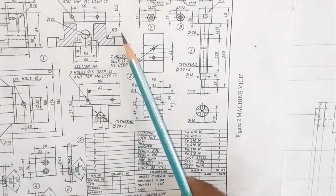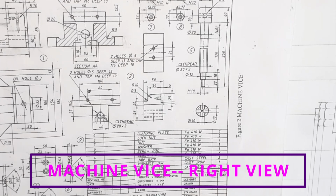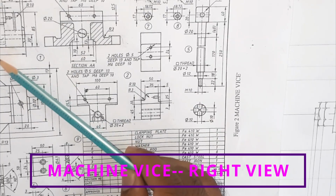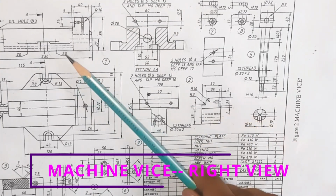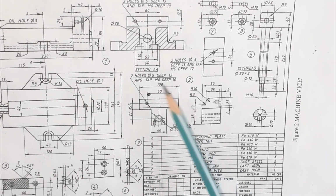Okay, so first let's draw these side parts. At the bottom, let's draw a straight line of length equal to 180 mm. Then let's draw a height here on both sides of length equal to 23, which is given in the front view. So let's draw a line of 180 and height of 23.